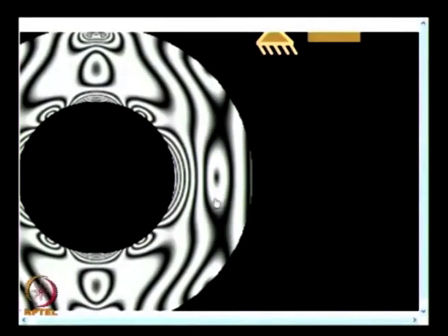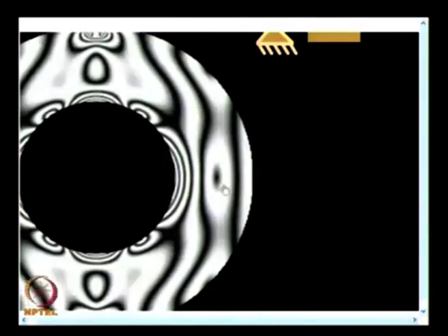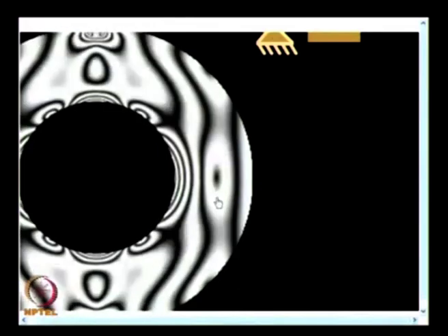After my telling you this, you should observe it. In this zone, fringes come out of it and then they become denser and denser, and this remains as such. And we have had enough clue earlier. We had said what the zeroth fringe order is. I said the zeroth fringe order does not move even when the load is changed, isn't it?